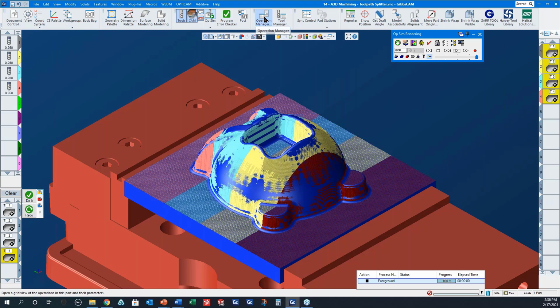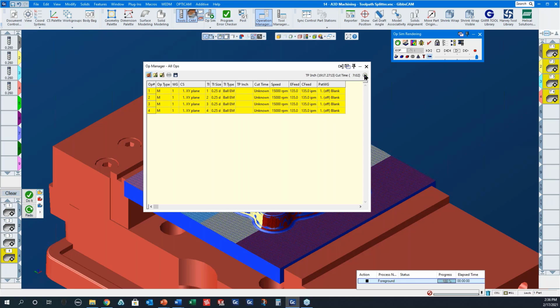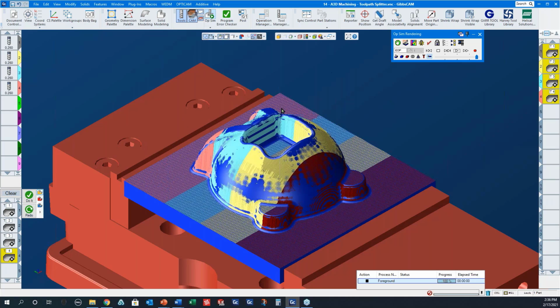And again, if you wanted to see the toolpath differences, 439, 441, 440, and 435. Very similar cycle times. This is also handy if you've got a machine that has a limited amount of memory. You could do this and post the code for different operations so you could break your file up automatically, not have to do that in an editor.